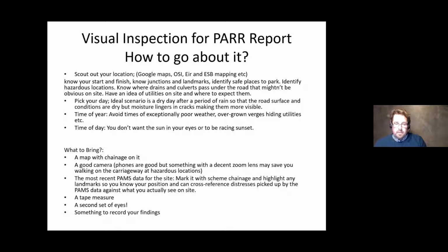Bring your PAMS data. Bring your PAMS data with the chainage marked on it, with your identifiers and your locations marked on it so that you know where you are and you know when you identify a failure or a distress on the site that it has been picked up or not picked up by the PAMS. And you can make note of that and cross-reference as you move forward. And this will also be critical when you go to get your FWDs, that you can highlight these locations for closer analysis. Tape measure, it might seem outdated, but if there's exceptional cracking or exceptional depths of delamination, you can just get a measure of it, literally get a measure of it so you know what you're dealing with.